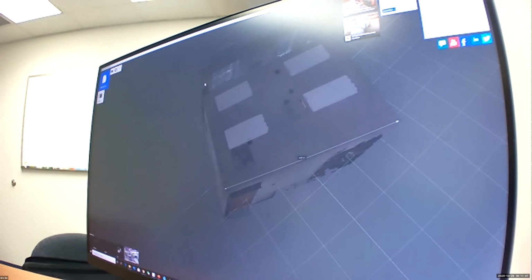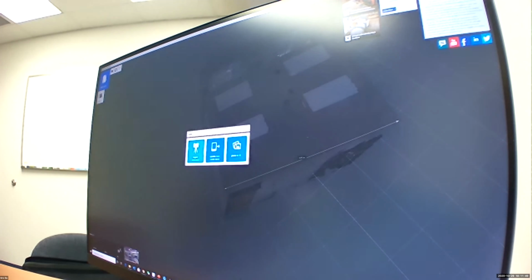All right. So let me open a new project and it asks me to import a point cloud model, transfer from mobile device, or photo to 3D. So if you decide to use ReCap Pro to do your photogrammetry project, you select the third button. This is the photo to 3D. This one will allow you to load your pictures and do the photogrammetry. So now I'm just going to connect to my mobile device. So I select this one and hook up my iPad.